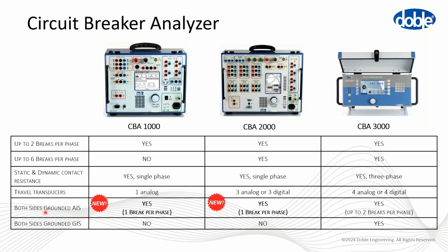It is more difficult to test in this condition because both sides are connected to the ground, which is connected to the ground grid. The ground grid has a quite low resistance, so that goes in parallel to the main contact one. This gives some difficulties when you test it, because basically you will see that the breaker is always closed due to this resistor.